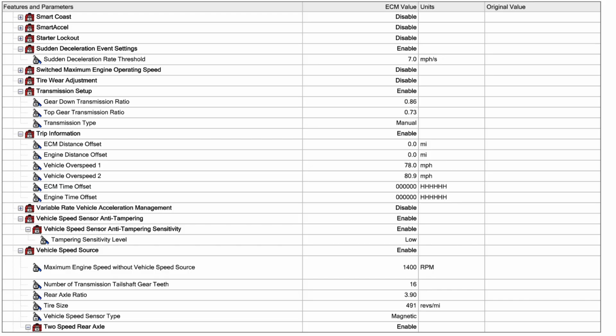Okay, vehicle speed source. That's enabled whenever there's a sensor, whether it's in an automatic transmission or a stick, that tells the ECM how fast you're going. And by the way, it tells the ECM drive shaft revolutions. That's all it tells it, just revolutions. It has no idea how fast you're going. That is all calculated by the calibration to be driver friendly. It looks at thousands of RPM in a minute to figure out speed source.